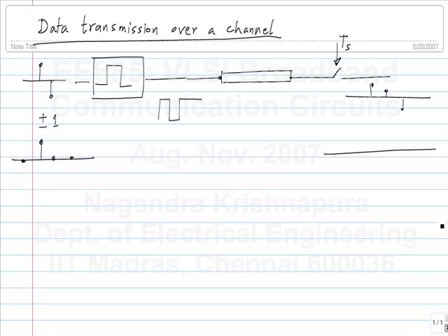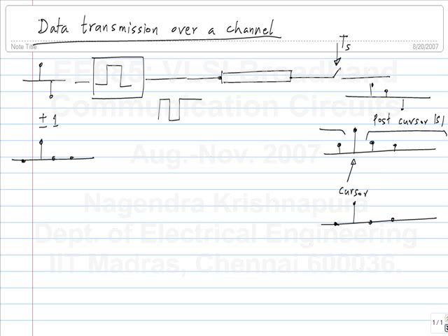The output, which ideally should be a digital impulse, consists of one main component which we call the cursor, and non-zero components before and after. Ideally it should have had only the cursor. We defined everything that comes after the cursor as post-cursor ISI and everything that comes before as precursor ISI.